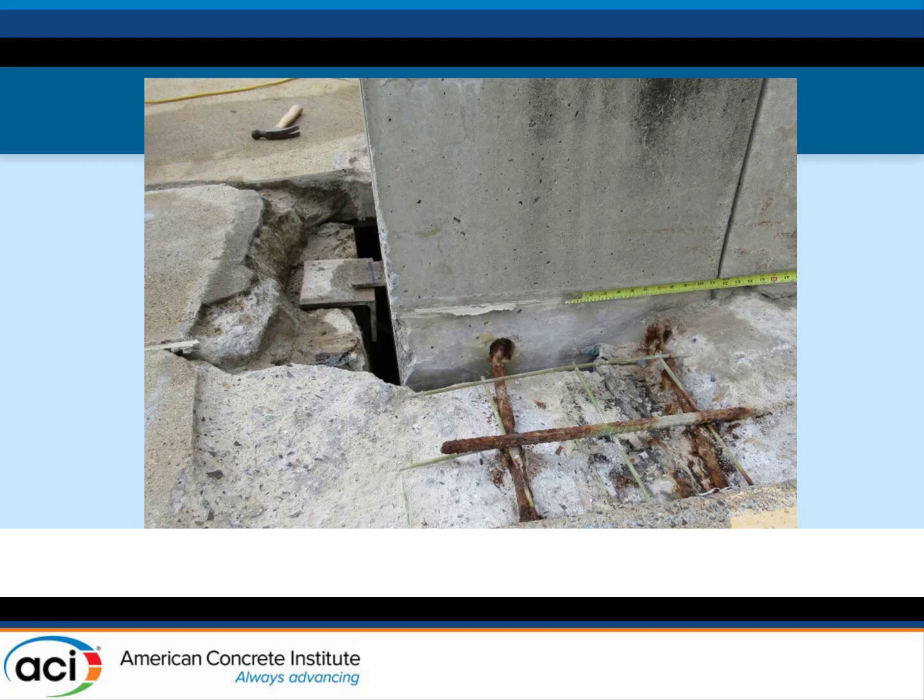There was a separation there. And that's consistent with the bars that you look at; you see how the bars are bent? I think that was the continuity reinforcing that they were running through the columns, maybe to meet some code provisions. So once you cut things open, now you've got a whole different thing going on. You've got broken connections in the garage. So it's not a matter of going around and just replacing all the sealants in the garage.